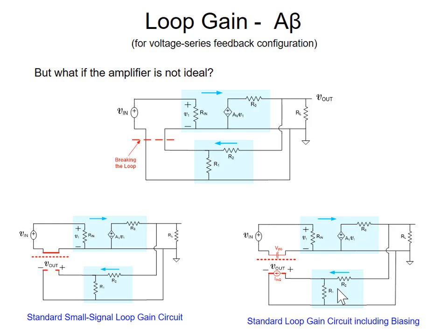But this voltage across here, if I break it this way, this current through here is 0. Actually, there's some current flowing through here, and that current will be the quiescent current. So what we want to do is terminate this side here. This is good for small signal analysis, but not for large signal operation. So we would like to put a DC current source in here equal to the quiescent current that would have been flowing there. And this is an AC short circuit.